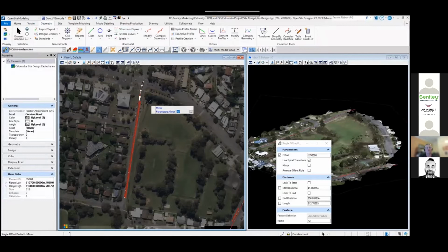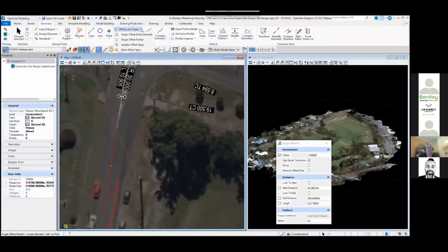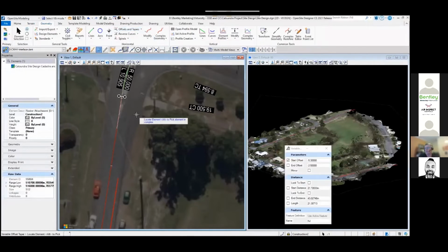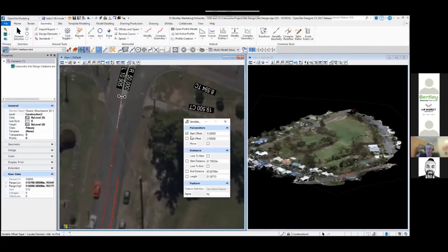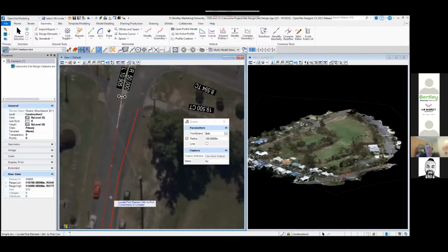I'm using some geometry tools here to define where that cut line, that join line, where that edge of full reconstruction is going to take place. It was also decided we're going to do a slurry seal over the top of Ulm Street at 7 mil, so some microsurfacing.